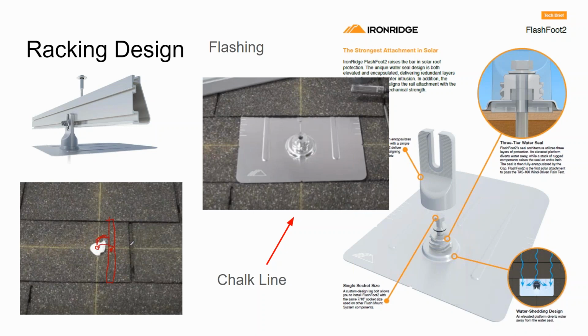With that old hole, you then insert sealant, and then that hole gets covered up by the flashing, which has additional sealant around it. So poking a hole in the roof, provided that you have a good, solid game plan for flashing around it, is not a big deal. Without the flashing, you don't want to make a mistake. You want it to grab on tight, otherwise it's not going to hold. But by far and away, the industry standard now is to have a flashed standoff on a shingle rooftop.